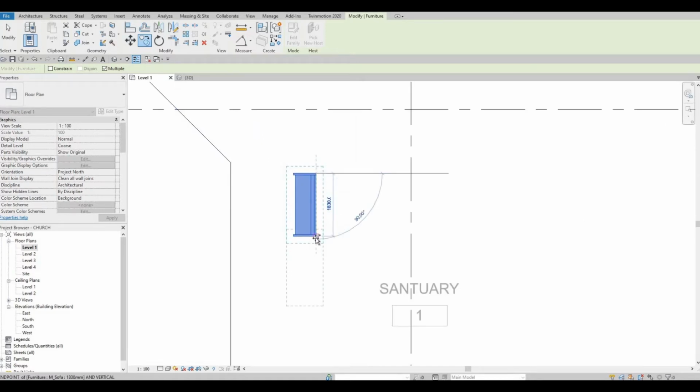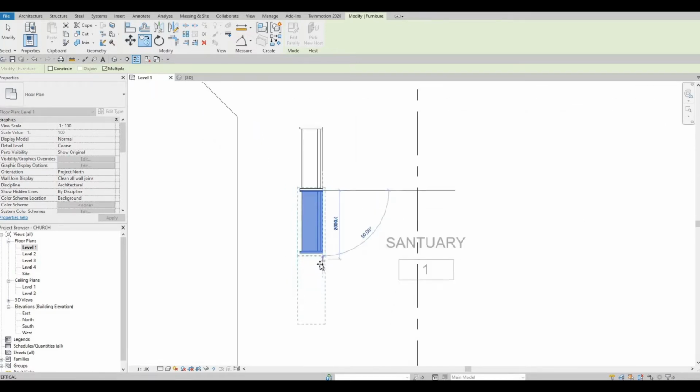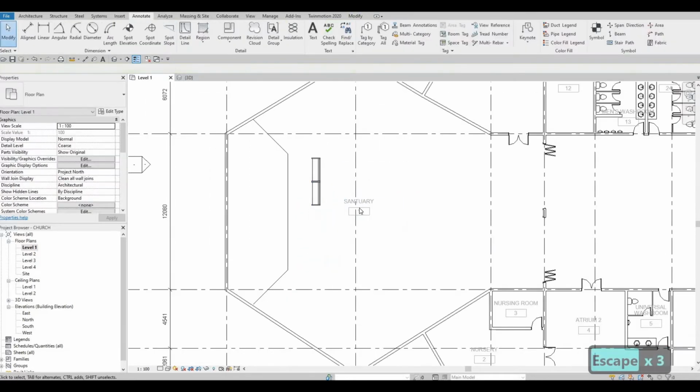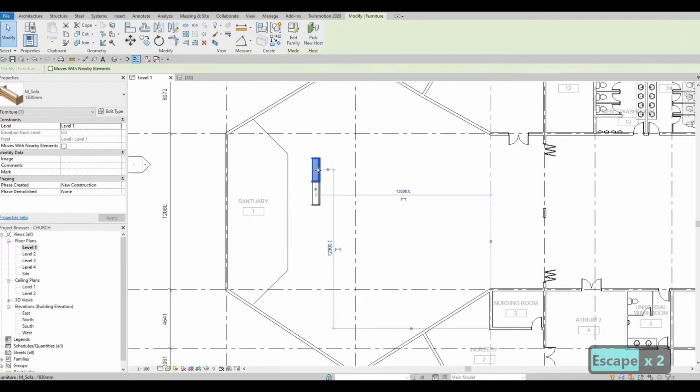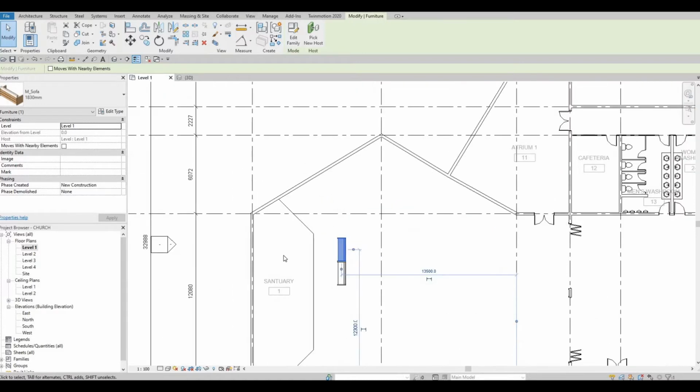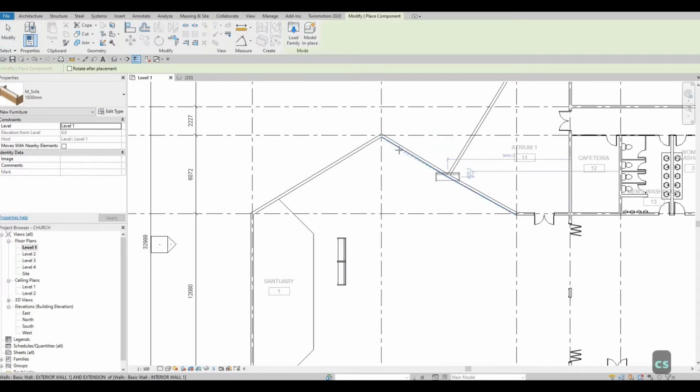So I'm gonna grab it from here, and most of the time it looks like this one. So we're going to put rows of 2 for now. Maybe we could add the one here on the side as well. So I'm going to select that, CS, and change the orientation depending on this view right here.